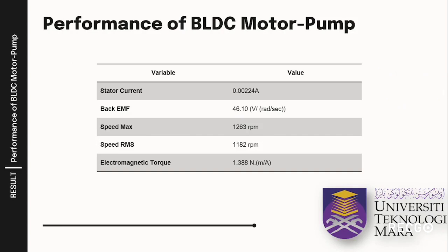For the characteristics of the BLDC motor, a 1050 RPM, 1 HP, 30 volt, 3-phase BLDC motor is selected for this work. The behavior of the BLDC motor at 1000 watts per meter square, connected to a centrifugal pump, is used. The variables, which are back EMF, the electromotive force, and the speed, reach their rated value under steady state as MPPT is tracked.